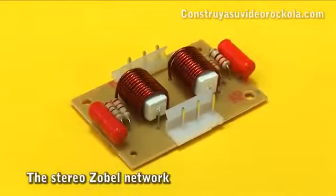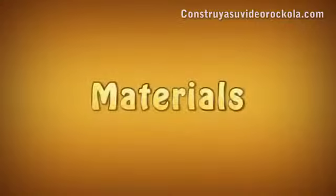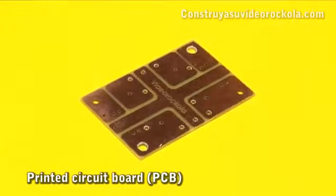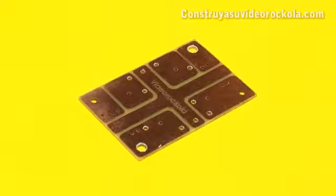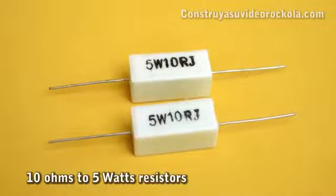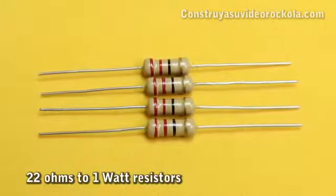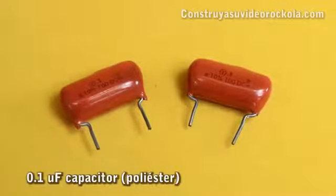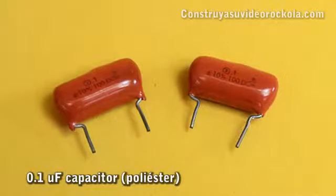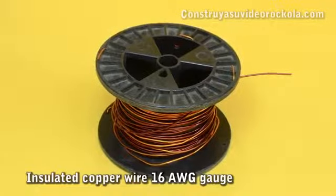Then we will see how to build a Zobel network, serving many amplifiers. Materials. Printed circuit board, you can make it in fiberglass or Bakelite. In the video description, you can download the PDF file. 2 resistors, of 10 ohms, 5 watts. 4 resistors, of 22 ohms, 1 watt. 2 capacitors of 0.1 microfarad, 250 volts. An insulated copper wire, 16 AWG gauge.